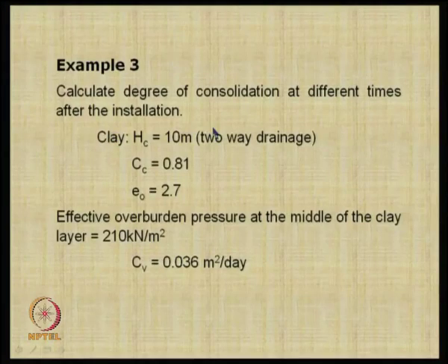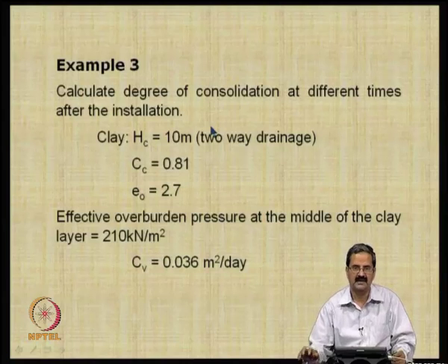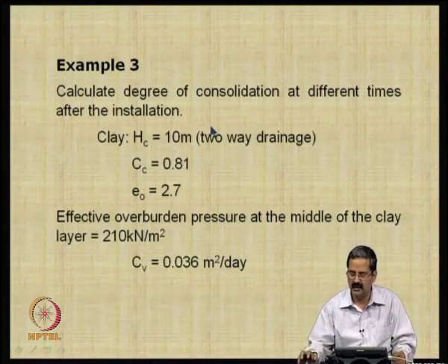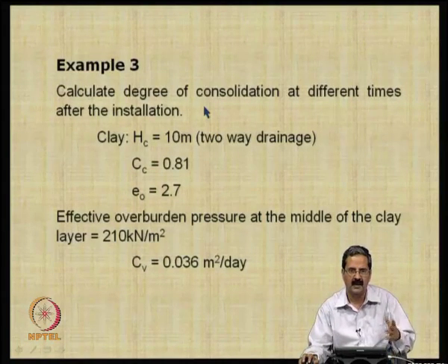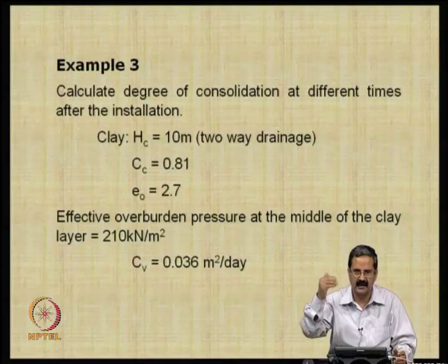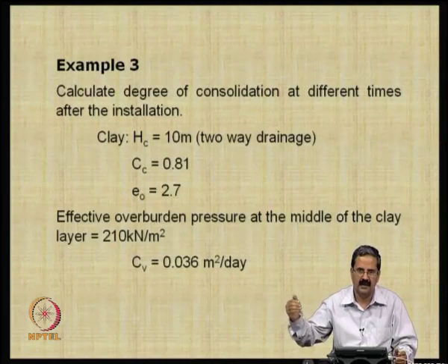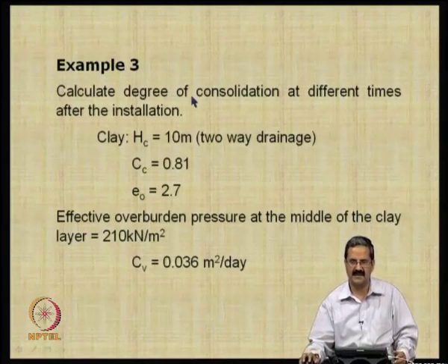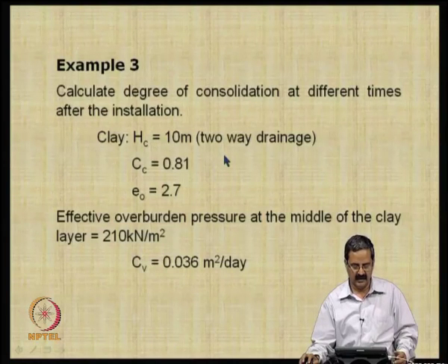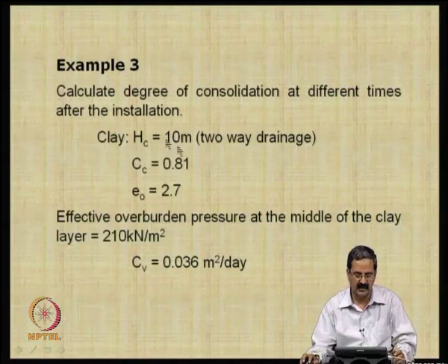Another important point that we have to calculate here is that you should be able to calculate degrees of consolidation at different times after installation, because we know that this consolidation can be very low, and then we would like to increase the consolidation using the sand drains or prefabricated vertical drains. For a similar typical example,